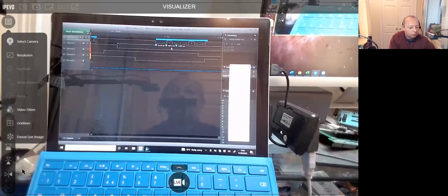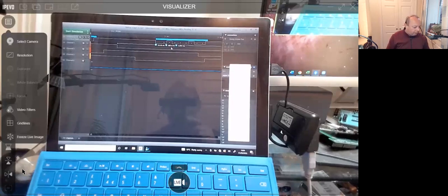So it's a great tool for debugging electronics, things like I2C, SPI, UART. Certainly with I2C, which is address-based, you can see with these sorts of tools exactly what address you're sending, and whether you're getting an acknowledgement back from the device. So then you'll know, okay, I've clearly got the wrong address, or the chip's not working properly. So I highly recommend you treat yourself to one of these.